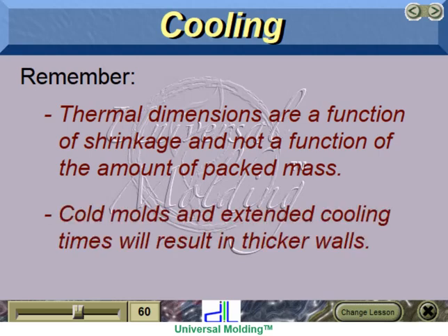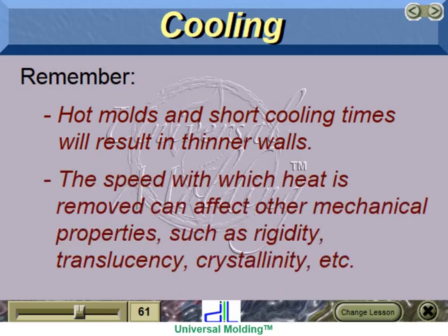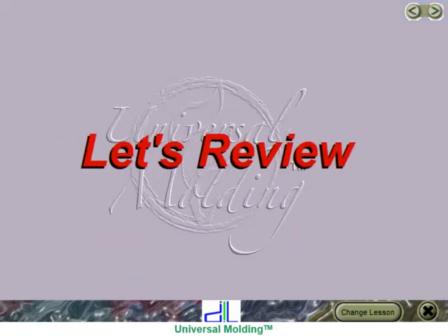Cold molds and extended cooling times will result in thicker walls. Hot molds and short cooling times will result in thinner walls. The speed with which heat is removed can affect other mechanical properties, such as rigidity, translucency, crystallinity, etc. Let's review.